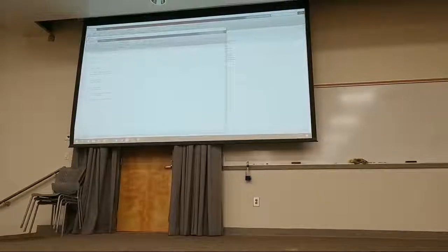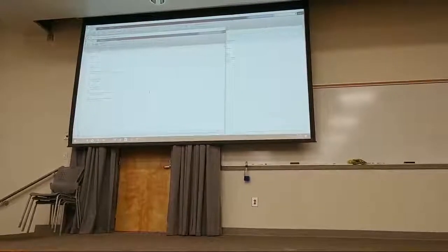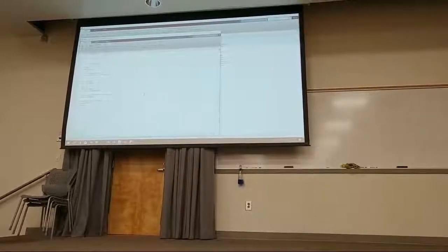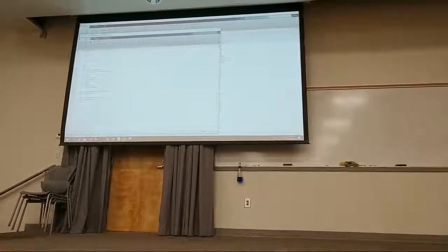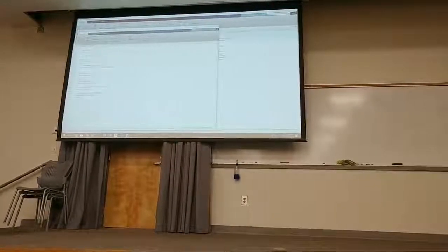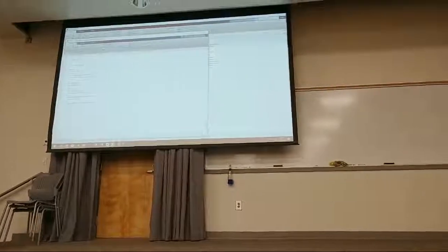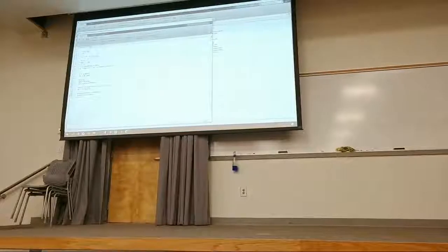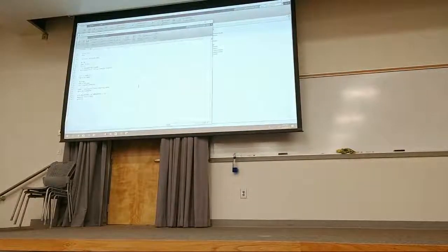Now that that's done, I don't know if you did the homework or not, but what I did was assign something using that relationship I showed last time, where you can take the quantity 1 minus e to the minus j omega t, divided by j omega, times the actual DTFT or DFT of something that you can get in MATLAB and compare it directly to the Fourier transform. Do you all remember the lecture? Well, one of the things you could do is some of these comparisons.